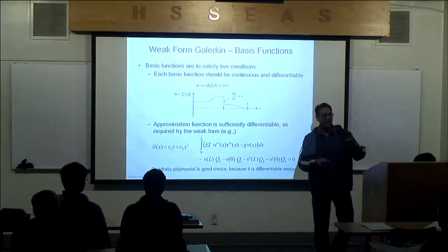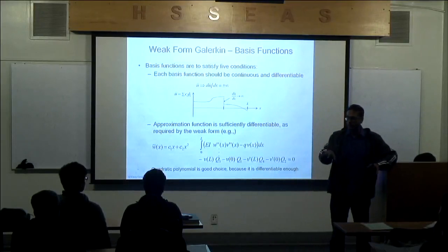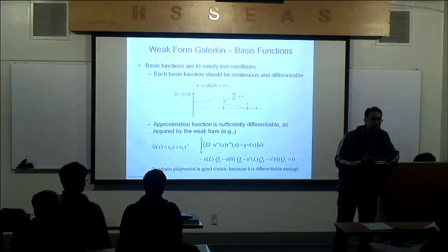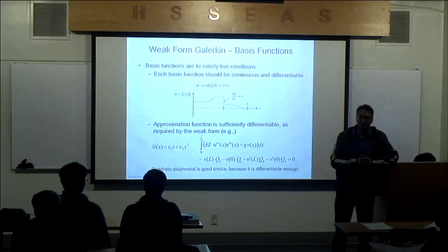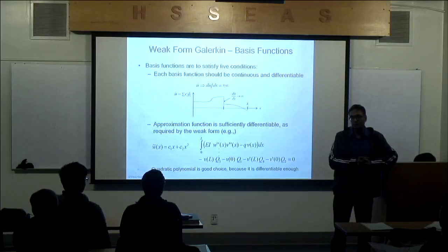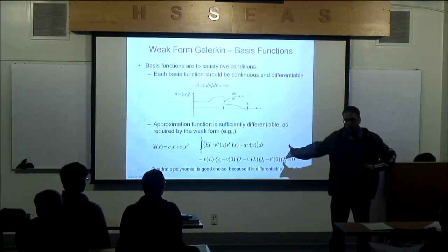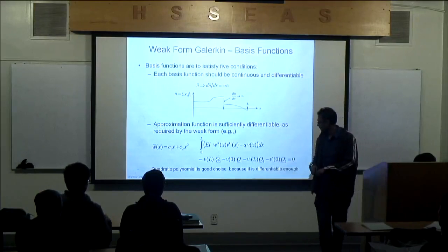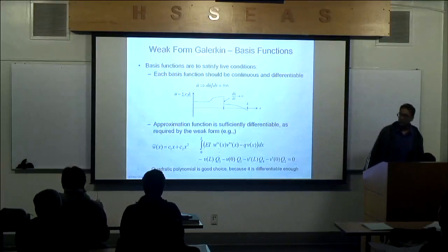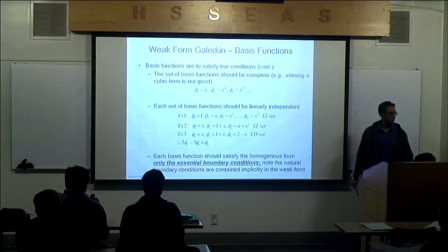Euler-Bernoulli beam theory in Abaqus, by the formulation that's typically used, normally uses a cubic polynomial for the approximate solutions. So this won't be a problem. This question you have is not a problem because we'll be using cubic polynomials. But you do have a great point that using a quadratic polynomial would have made that zero, this boundary term in here, the shear term. Okay. All right. Any questions? We're good.